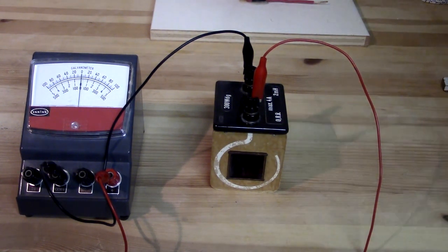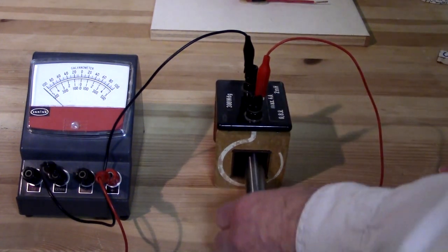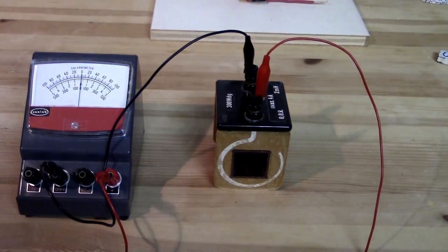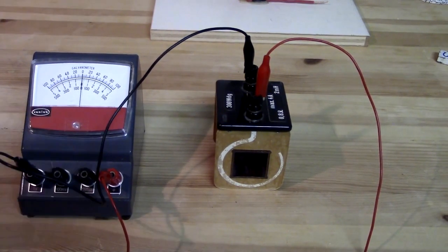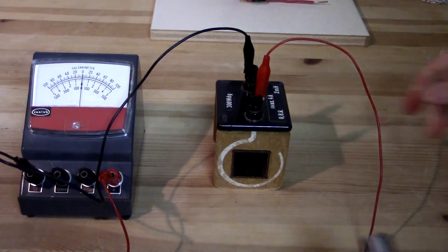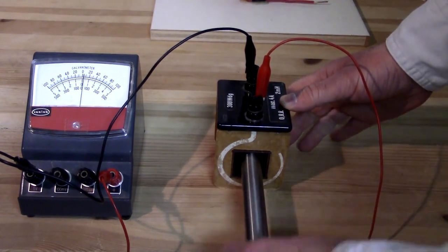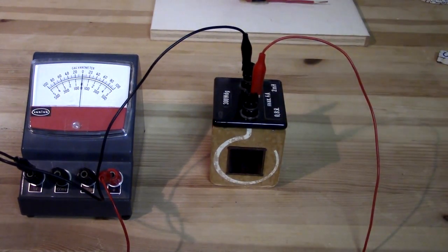I'm going to go now to the stronger magnet, and when I move the stronger magnet in, it's going off the scale now with the millivolt scale. So I can go to an even higher scale now, which is a 5-volt scale. So if that needle is deflected all the way to the edge on either side, we're talking about 5 volts. Well, you're not even going to get close to 5 volts. If I had to estimate, we're looking at maybe 0.2, 0.3, 0.4 volts.